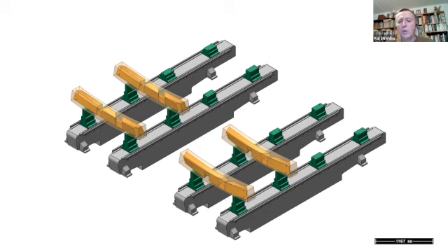So rather than using a Cambium for a Hundegger machine or a traditional CAM software, we have produced our own script software from Rhino. We are scripting in Python, and we are using the geometry from Rhino, and out of the geometry, we are directly generating the G code for the machine and producing it on the machine.